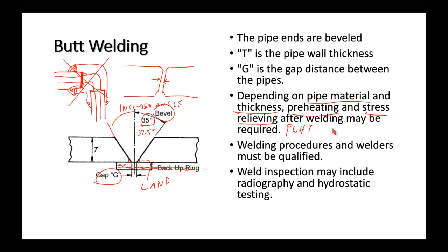If you recall, martensite forms when we cool off metal extremely quickly, and it forms that brittle body-centered tetragonal structure that we call martensite. And so that's what we don't want to form. So what we can do is preheat the metal that's being welded so that the weldment cools off slowly, or we can post-weld heat treat it afterwards. When we get into welding, we'll take a look at more of those techniques.